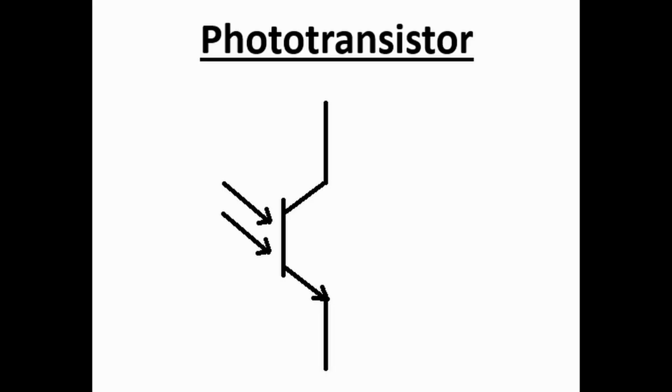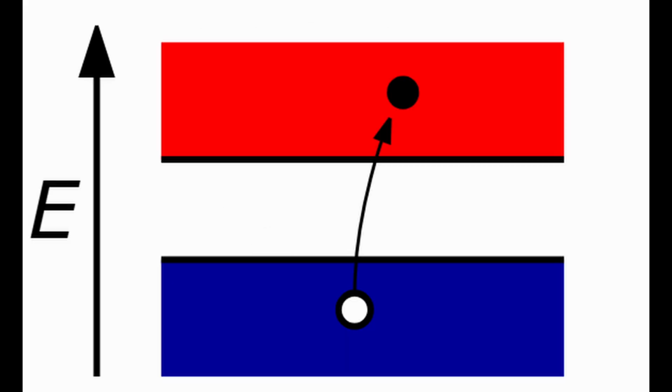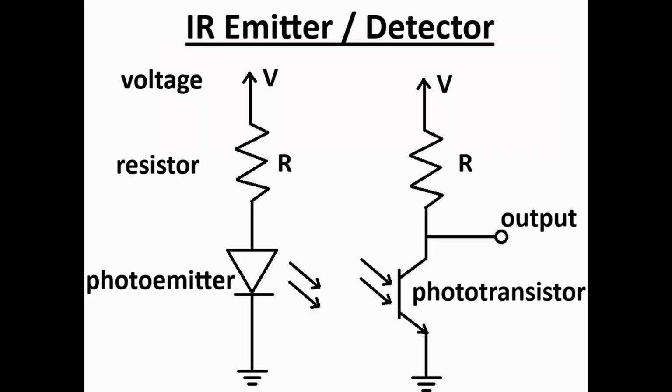A phototransistor is like a switch that is controlled by light. It allows current to flow through it in proportion to its exposure to infrared light. The incident light creates electron-hole pairs, which are charge carriers, to produce a current in the semiconductor material within the phototransistor. The distance in separation between the photoemitter and the photodetector results in a proportional signal current, which is a measurement of the physical displacement.